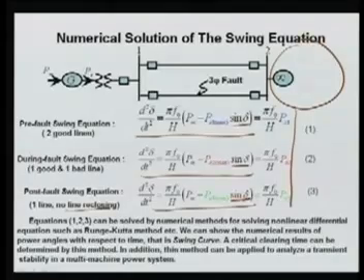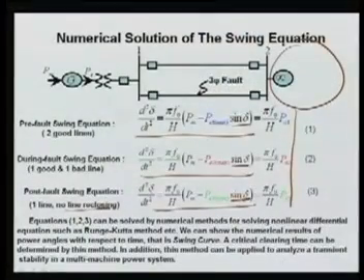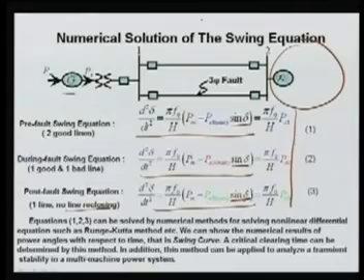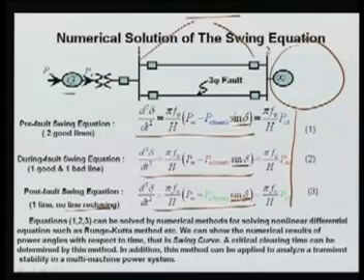There will be several generators, and again, this generator is not a classical generator. A classical generator means a generator modeled in the classical form, where we have taken only the generator with some inertia constant. Then we can go by several orders of modeling of the synchronous machine. It will be equipped with excitation as well, and with the governing system. So all dynamical equations will be clubbed together along with algebraic equations, because the power flow of the different transmission lines will be there. So we have to form these algebraic equations, and then we can solve.